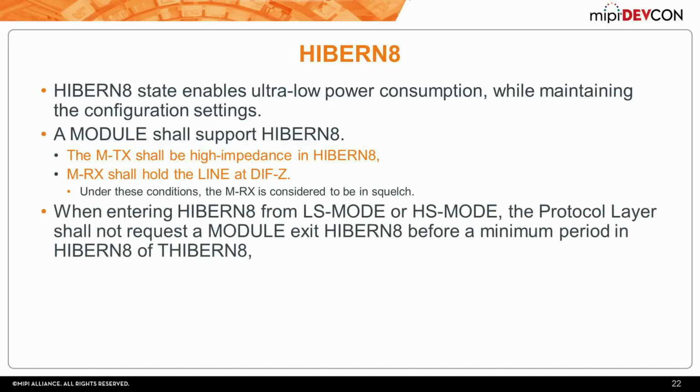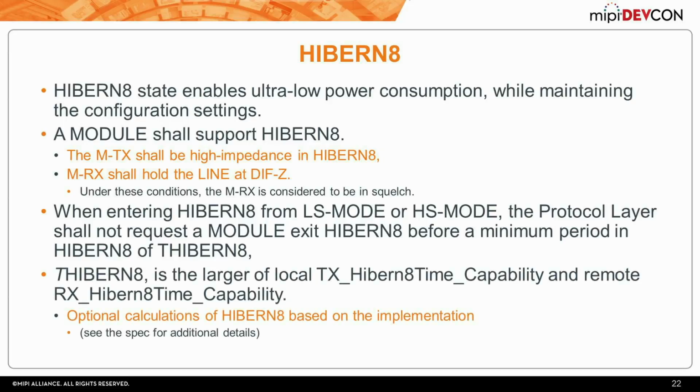So when you enter Hibernate from low speed or high speed mode, then the protocol, so the upper layers, mustn't request that the module exit for a certain period of time. So it doesn't make sense if you go to a Hibernate state and then just stay there for a short period of time. It's not useful for power saving, so it must stay in for a minimum period. And those are defined. The calculations are based on the implementation though, so you can see that in the spec.